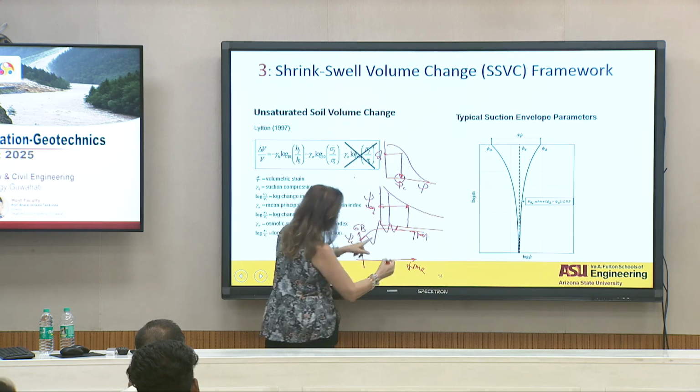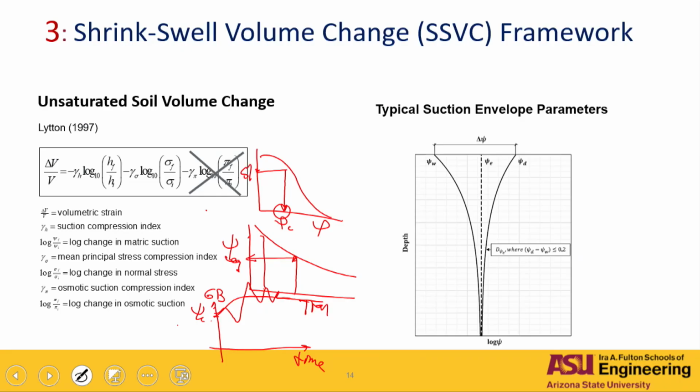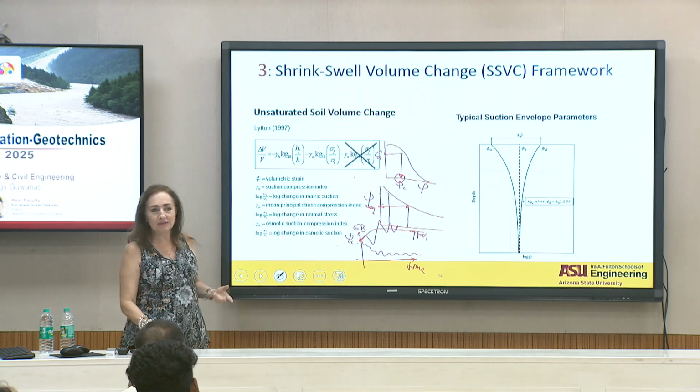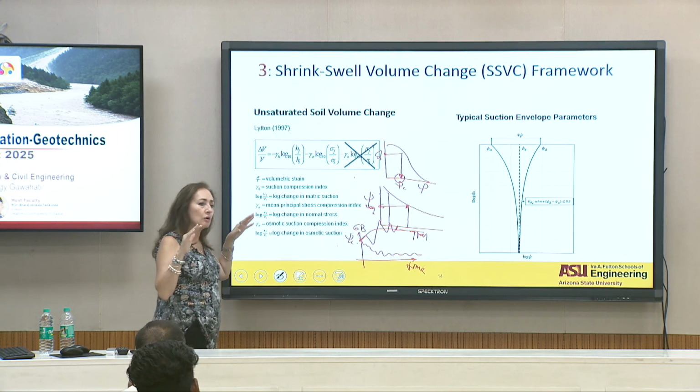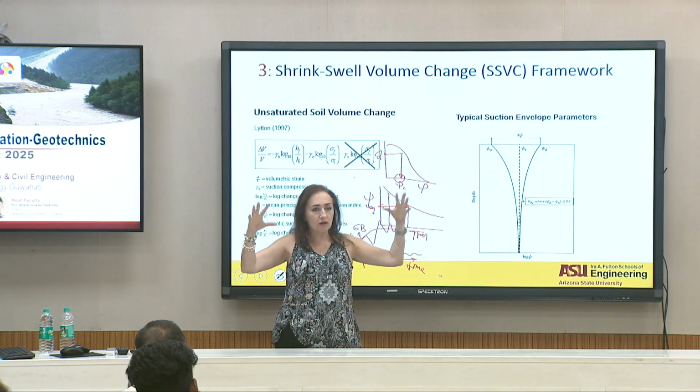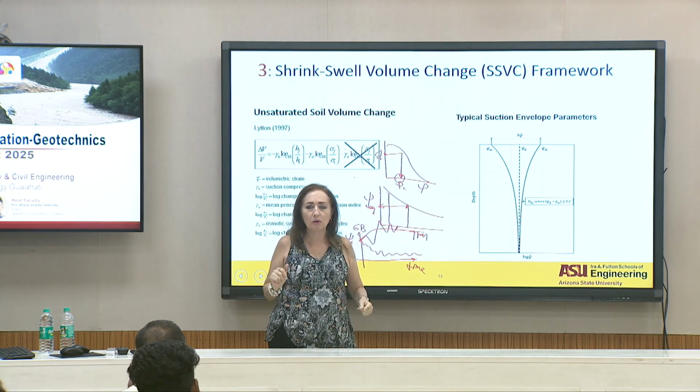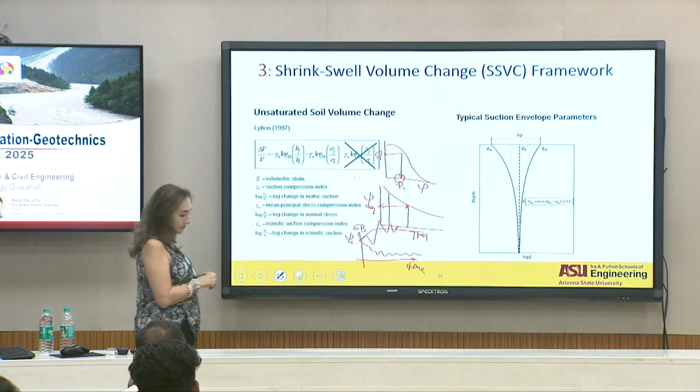So for Arizona, you're going to see that one, but for Guaha, you're going to see that this guy is going to go down in here until it equilibrates right there, okay? So that's the assumption that we made. Soil will tend to equilibrate to a condition, because if you have any way to get the water in and out, you will try to do that.